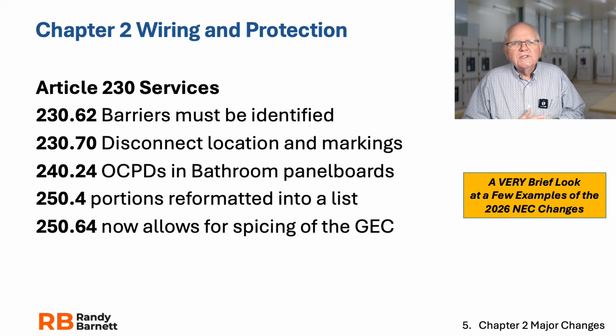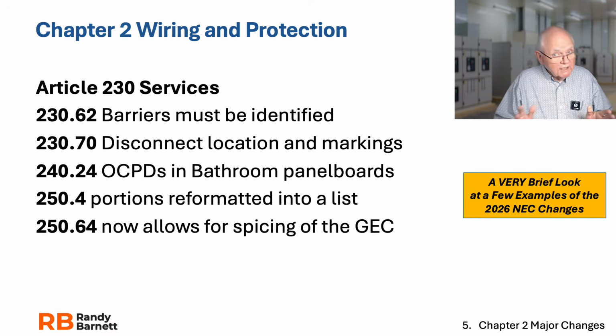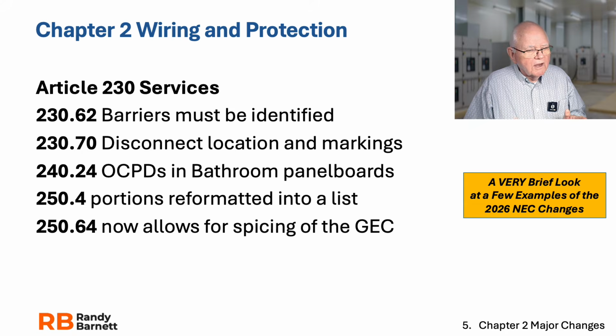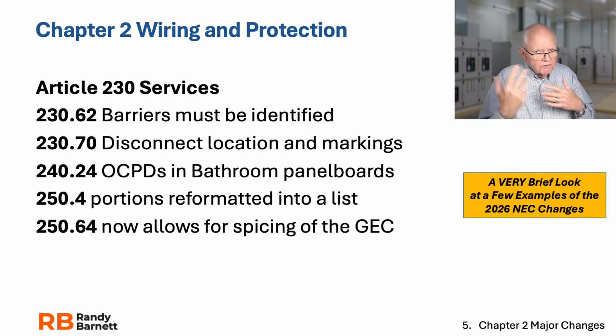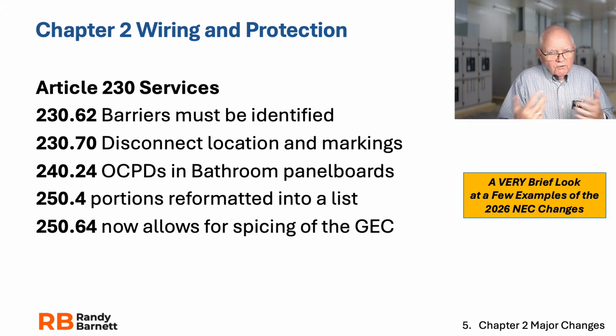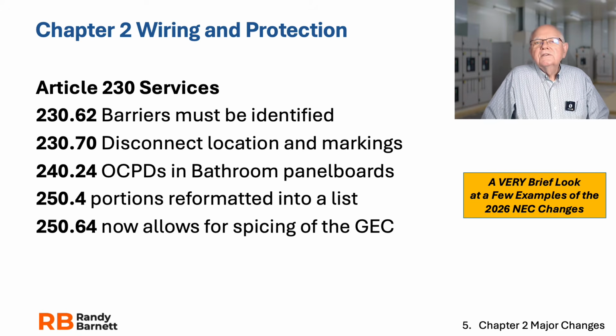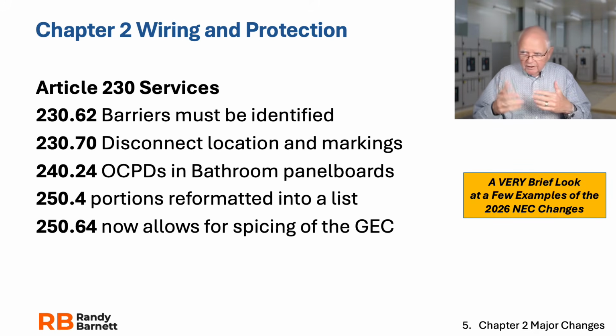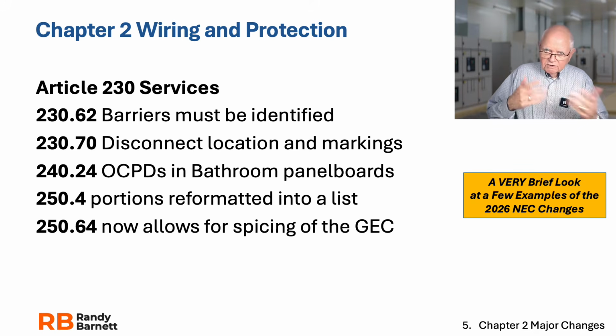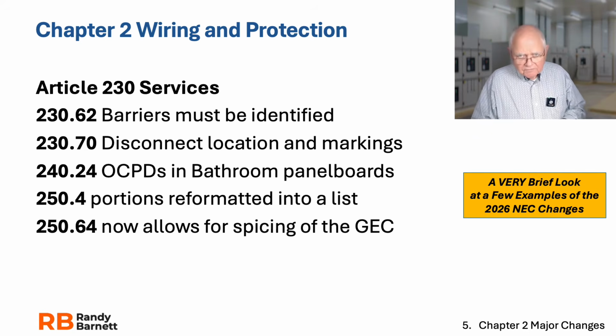Well, another thing we've seen now in Article 250, and some changes in Article 250, I'll tell you right off, right? They took all of that medium and high voltage information out and moved it elsewhere, and some of the limited energy information and so forth. But anyway, 250.4 is very important. 250.4 tells us why we ground and bond. And it tells you, so that we stabilize the voltage to earth during normal operation and so on and so forth, and why we bond and all this.